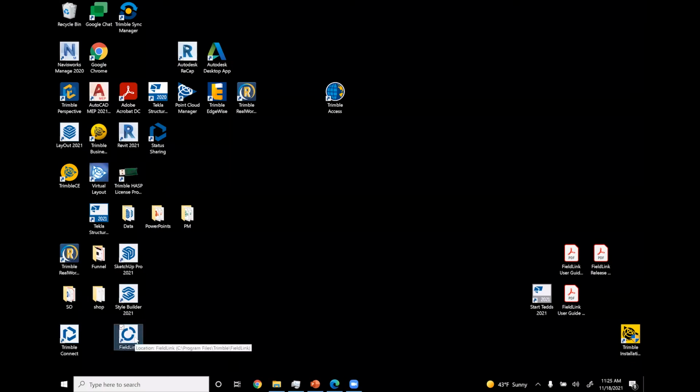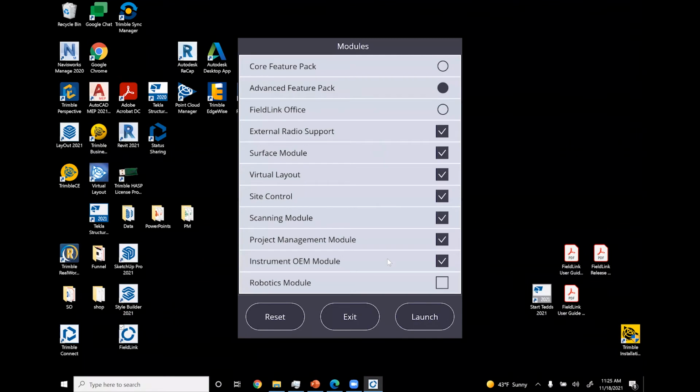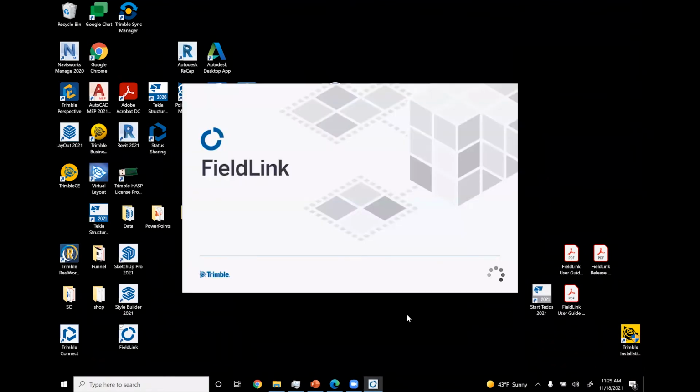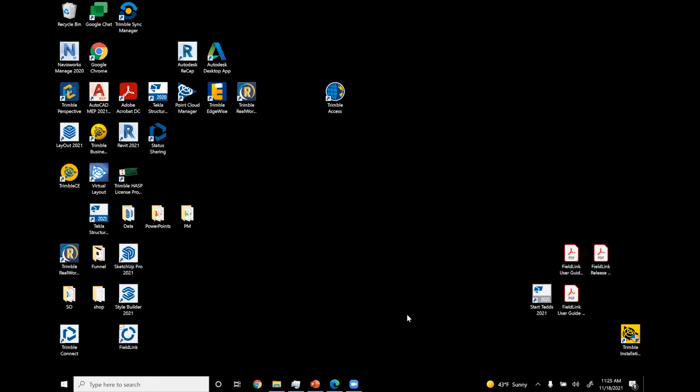One is to do a traditional resection like you would with your RTS, and that'll actually give you an error of the alignment. It'll essentially overlay it with a known accuracy, just like your RTS and doing layout, or you can manually pull it and align it, which I'll show you here in a second, which is generally what I train people to do. If you ever need to, you can always go back later and line up with the model or resection with the scan and line the rest of the scans up with that resection, essentially tying it into the coordinate system with a known accuracy.